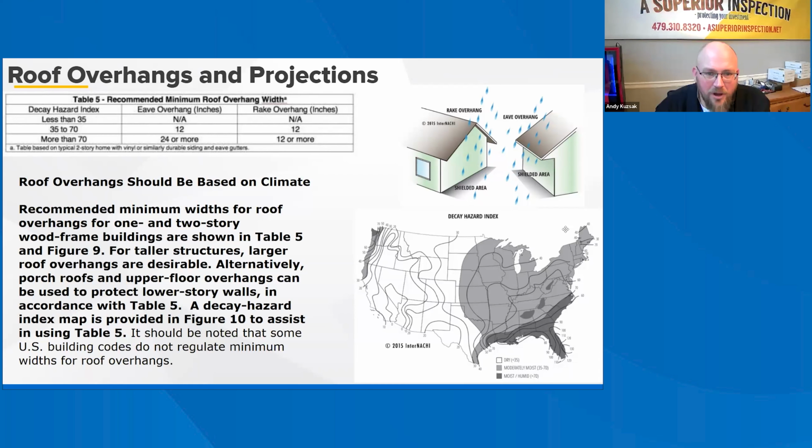So I'm sure all of us have probably come across an exterior door that has a larger sidewall going up above it, and no protective overhang or no roof line that covers it. And subsequently, when it rains, if the homeowner opens that door, if it happens to be an interior door, then they always get moisture intrusion coming into the house. So again, another reason why overhangs and protecting your exterior penetrations is super important.